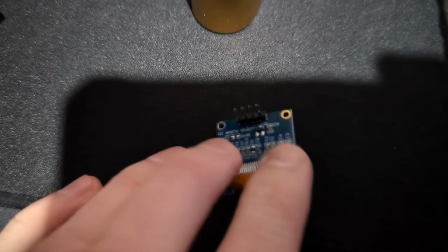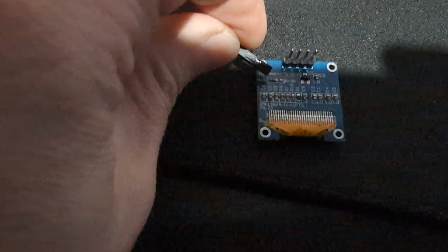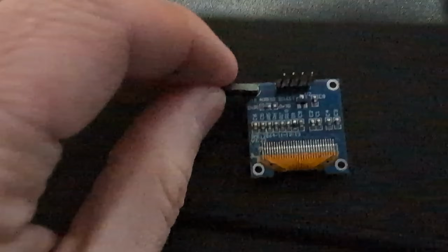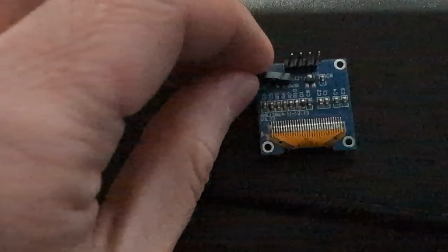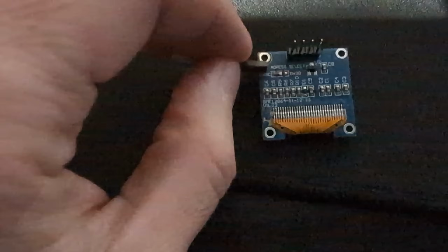So we're actually going to have to take, see if I can get something to make it a little easier to show you guys, we're going to have to take that one off, unsolder that one. I have to unsolder that little resistor and then bridge it between here, which is going to be quite painful. So that's how we're going to change the address. That's why it was displaying the same thing on both displays, because they were both the same address. So I'm going to go do that now.